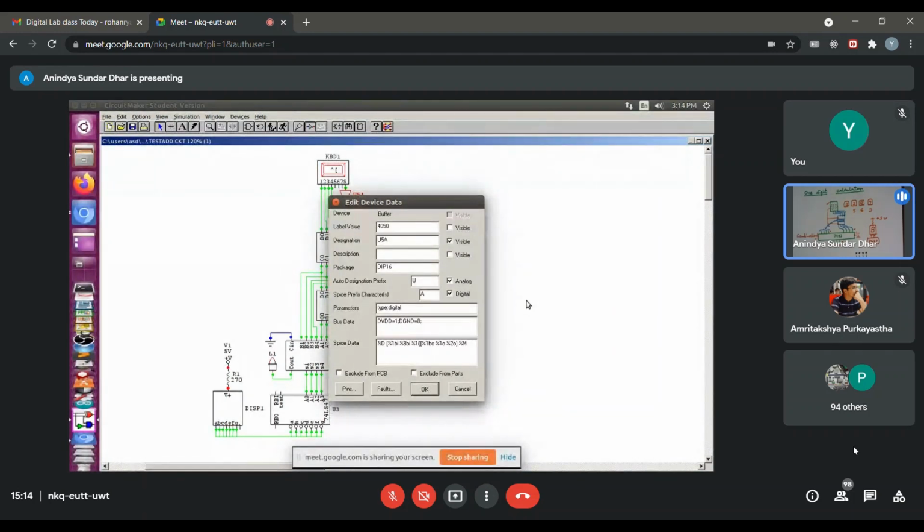And the number is 4050. It is basically a CMOS buffer. I think in TTL there has been some problem, so I used a CMOS buffer. So you may note down the number. It is probably there to generate that delay. Just now I was telling you that if the strobe signal comes a little earlier, then it settles. In practice, you will get sufficient propagation delay, but in the simulator, everything is ideal.